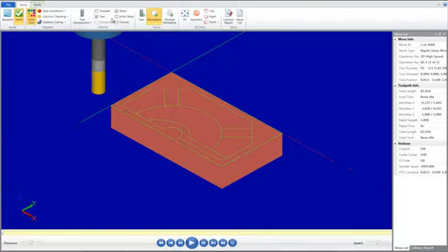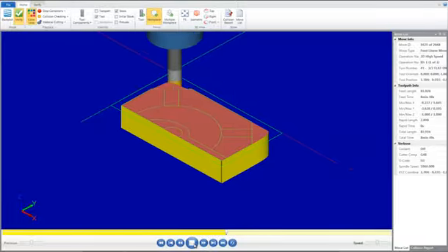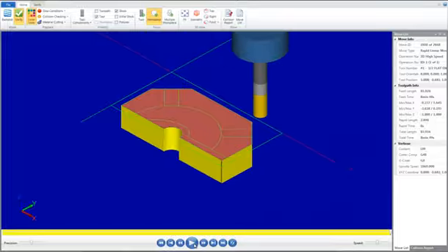Ensure that Tool, Stock, and Workpiece are enabled. Verify mode shows the path the tools take to cut the part with material removal. This display lets you spot errors in the program before you machine the part. As you verify toolpaths, Mastercam displays additional information such as the X, Y, and Z coordinates, the path length, the minimum and maximum coordinates, and the cycle time. It also shows any collisions between the workpiece and the tool. You can now select the Play Simulation button to run Verify. Your part will appear as shown up to this point. You can now exit Verify.